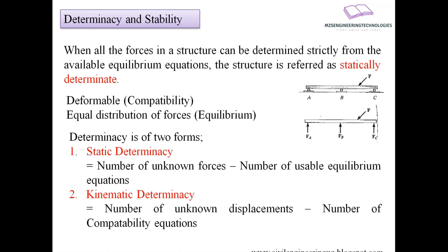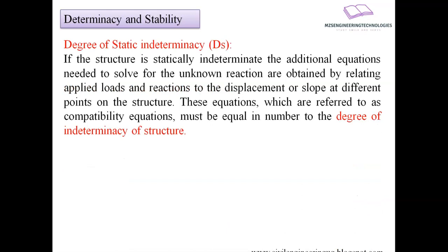In terms of kinematics, I'm going to find that the horizontal component of the applied force is not going to be balanced by any restraints available there. That's why it has insufficient constraints. So we can term this type of structure as statically or kinematically indeterminate. So based on this, let's go with a term known as the degree of static indeterminacy.